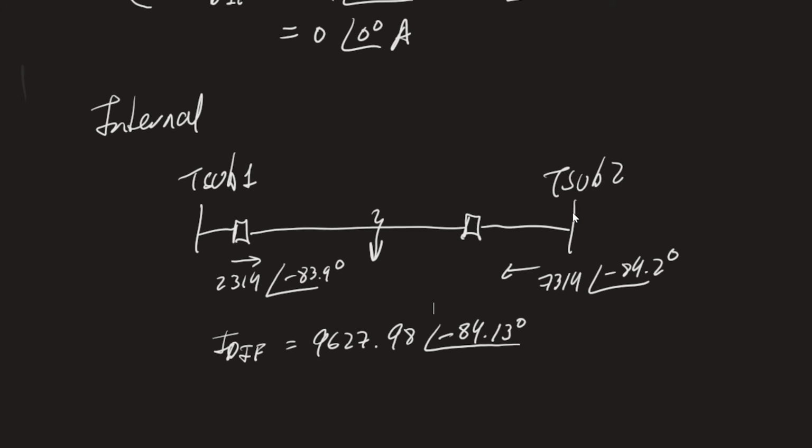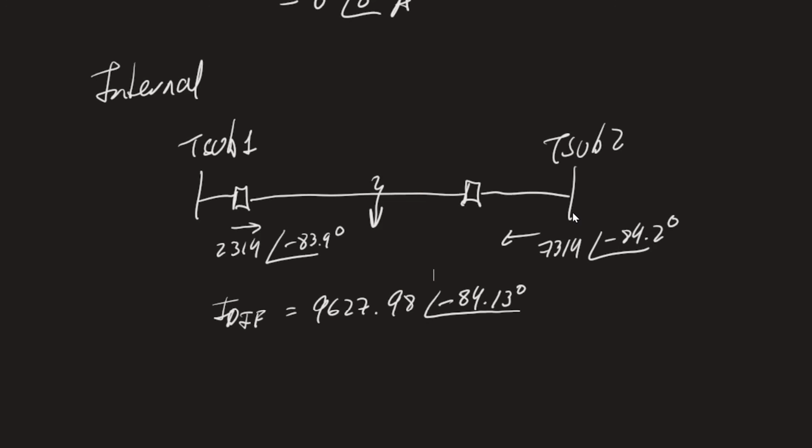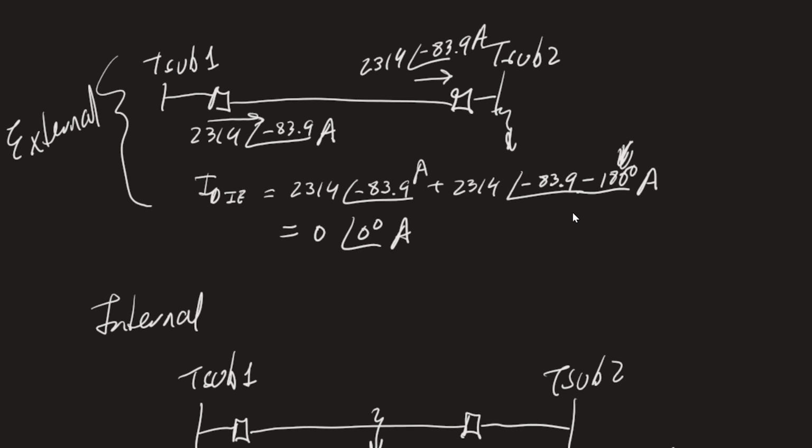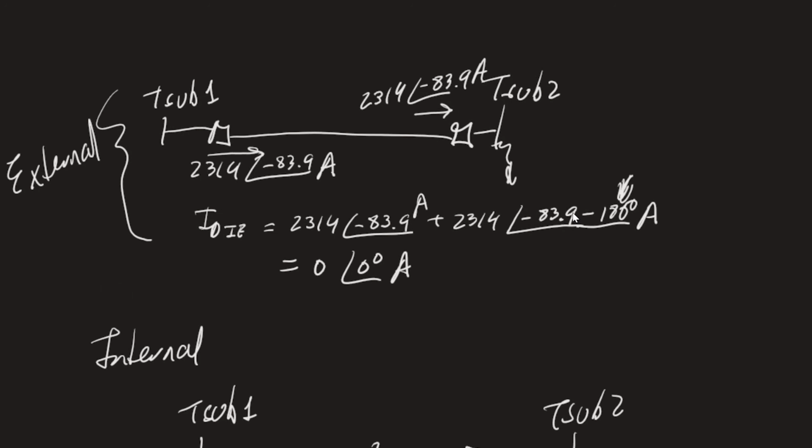And then for an internal fault, again, this is the ideal case where we're perfectly measuring everything, but this will vary a little bit. There's always going to be some error that is introduced by CT measurement errors, by the relay measurement errors, by just errors from the communications. So I just wanted to point that out. These numbers are for the ideal case, but of course there's always going to be some errors. And this is especially important for the external fault where we know that the current won't exactly be 0.